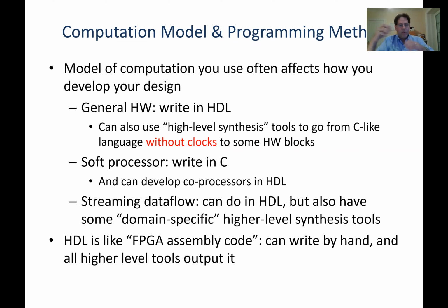High-level synthesis generally, compared to a very skilled HDL developer, usually doesn't achieve as high a result quality, but it is getting better. Another interesting thing about high-level synthesis is that generally to get good results from it, you need to still be thinking about the hardware that will be generated. So it doesn't mean you can just write any C you want and it turns it into efficient hardware.